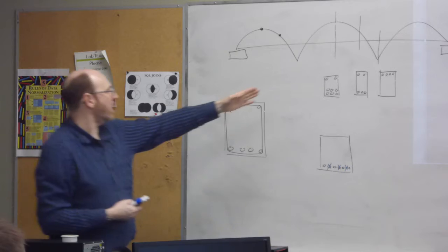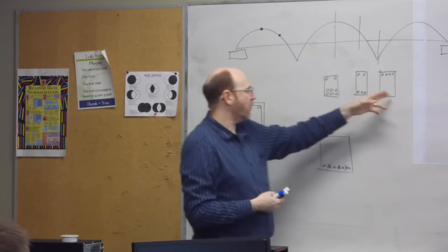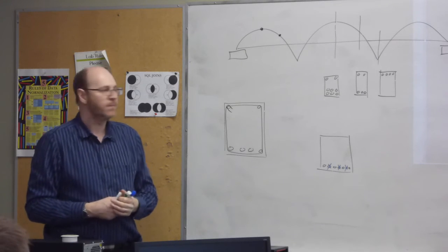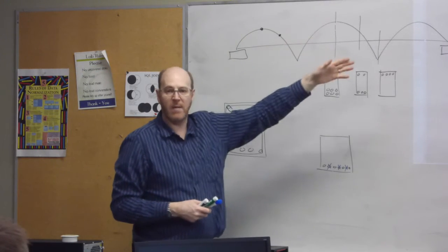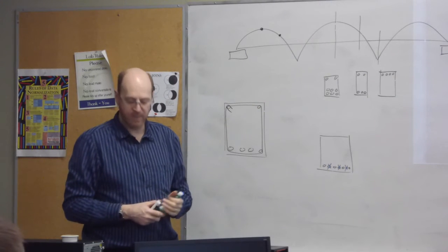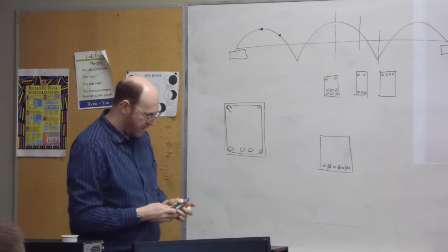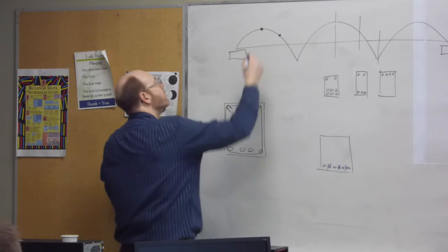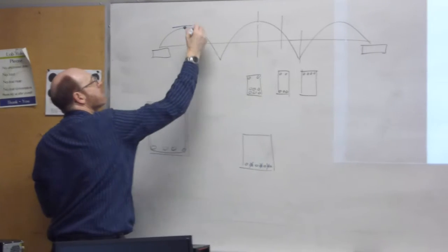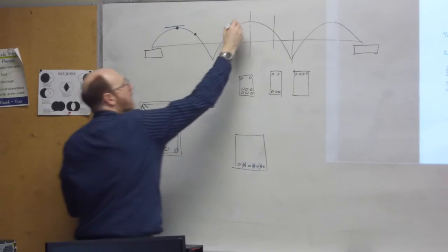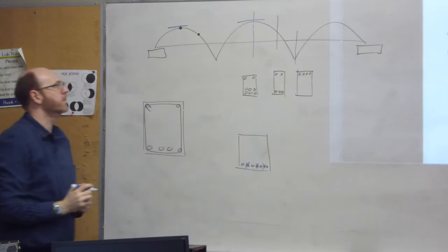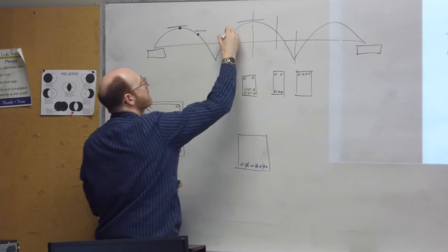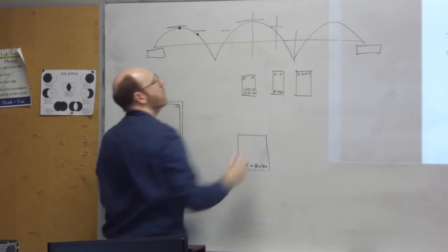Now, once you go through and figure out at all the various points what my reinforcing is going to look like, what you can then end up generating is a moment resistance curve. So here we've got our moment diagram. Technically, we'd have a moment envelope with all the various curves. And what we'd be looking at is, as I go through my various configurations, plotting up what that moment resistance looks like. So, right at my high moment region, I've got a particular curve that I'm looking at over here. Then when I get down to the lower region, I've got a curve that comes out like that. The same thing is going to come out over on this side and so on.